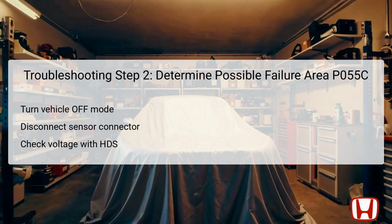0.18 volts or less. If the reading continues to fall within the same threshold as observed prior, it signifies that the issue may lie elsewhere, prompting you to move on to the next step for further diagnosis. However, if the reading diverges from this threshold, it implicates a more significant issue with the rocker arm oil pressure sensor or its immediate circuit setup.